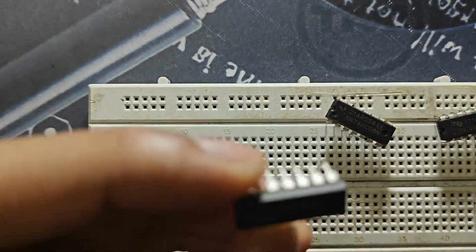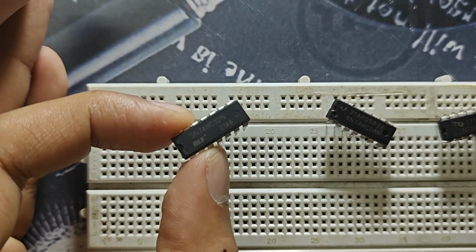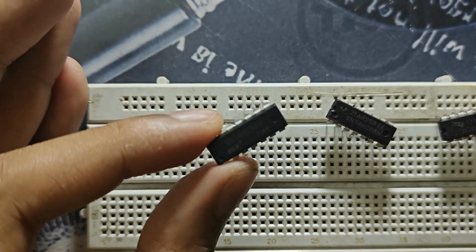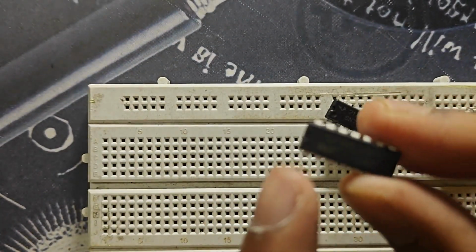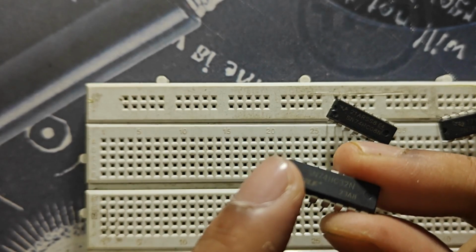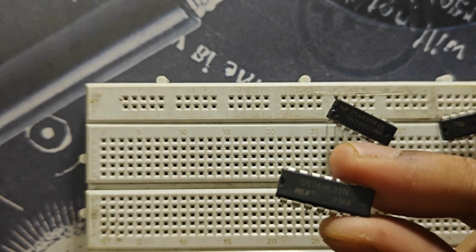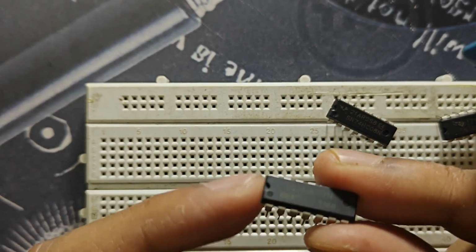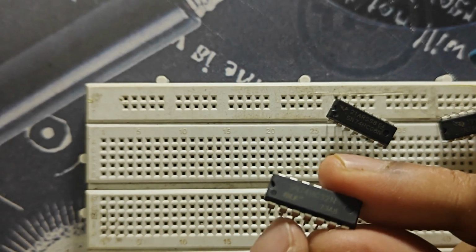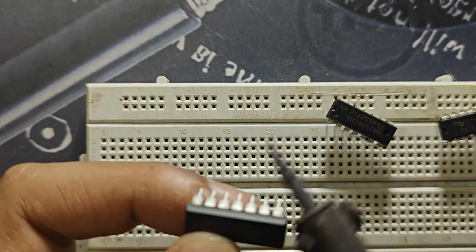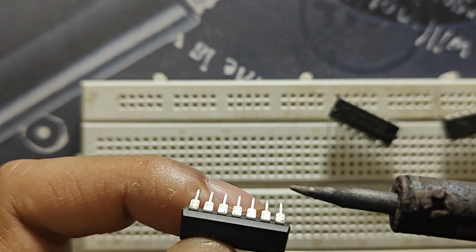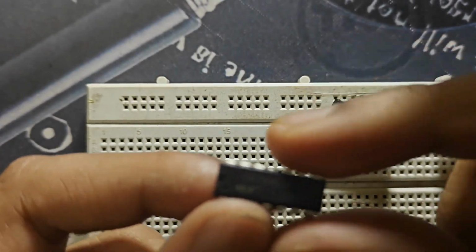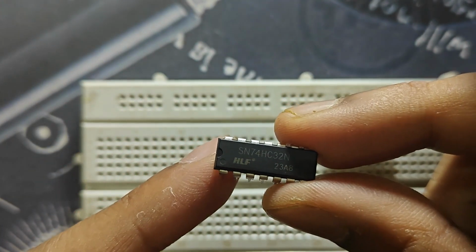So guys, this one here, as you can see, it's a 7432, and this is basically an OR gate chip. Now you will see under the light here that there is a notch at the front. This signals the direction, or from which direction you should count the number of pins. So from the direction with the bottom one is pin number 1, and it goes to pin 2, pin 3, and then up to pin 7 here, and then pin 8, pin 9, pin 10, and up to pin 14 here on this side. Okay, this is a 7432 as you can see in the video.